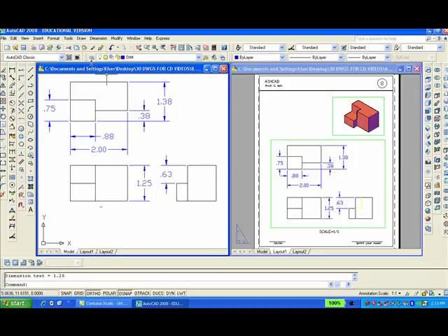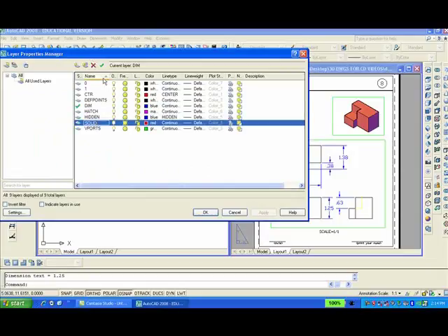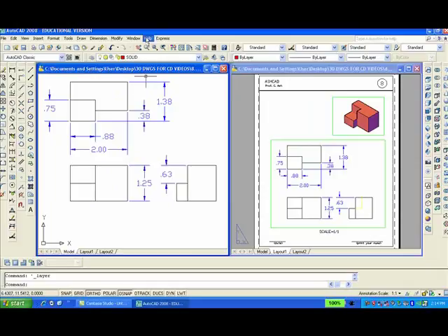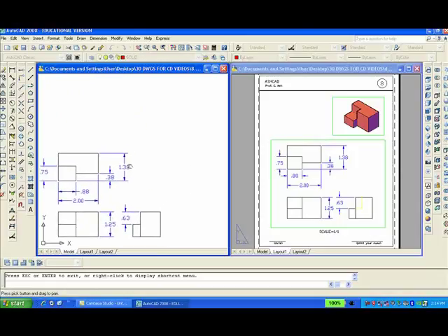Now we're going to make the solid model, so I'm going to switch here and make solid current for the layer. I'm going to zoom this down a bit and then pan over. So what I need here is a polyline.